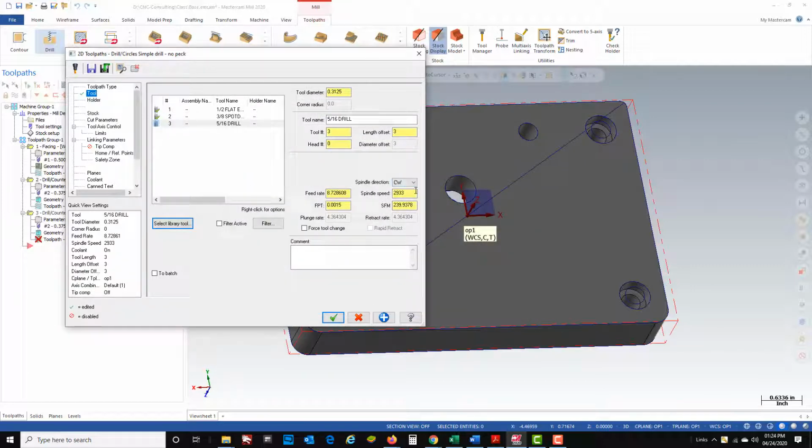Now, my drilling feeds and speeds are a little bit different because I'm not using carbide. I'm going to be using high-speed steel drills. So I'm just going to go with 200 surface footage because we are cutting aluminum. And then I'm just going to go 1% of the diameter, which is 0.0031. So we're at 2444 RPM, 15 inches a minute.